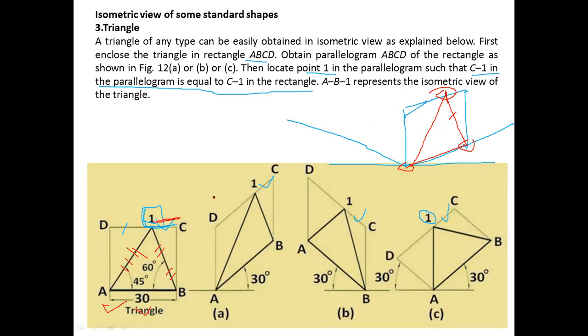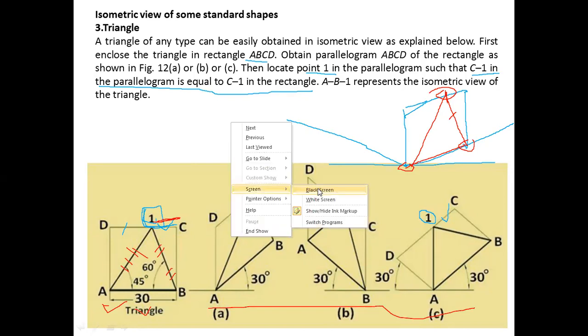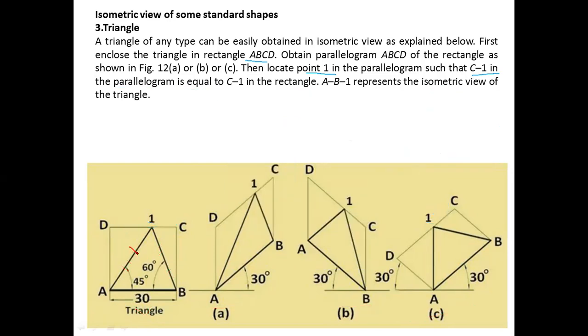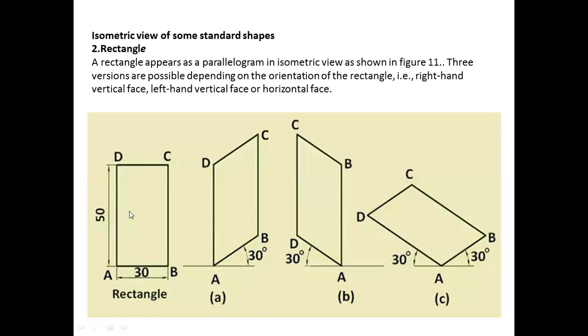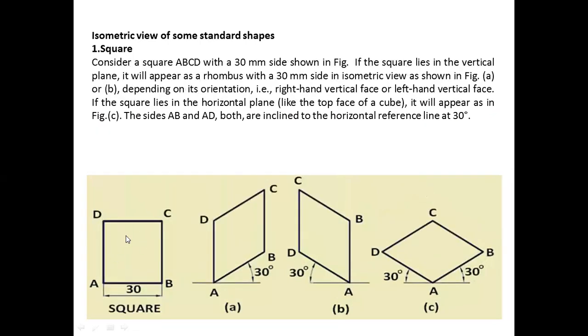Same happens on the left hand face also, or say the top face also. Understand? All three we can do similarly. But the thing different here is that you can't draw this directly. You need to find this endpoint, and then join your inclined line. That is the thing. Fine. Here we are having straight vertical, horizontal only. Here also we are having horizontal and vertical only. That's why you could have drawn it directly. Understood?